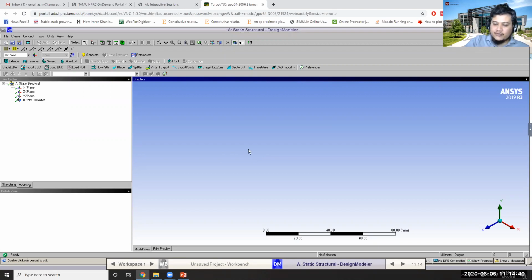For extruding anything, you need to have the cross-section shape of whatever you want to extrude. So if you're creating a three-dimensional shape, for example a cube, you start with a square and then pull the square in the third direction to create a cube. This is a very important feature, which you will come across on any 3D modeling software. Extrusion works both ways. It can add material to your geometry and it can remove material from your geometry.